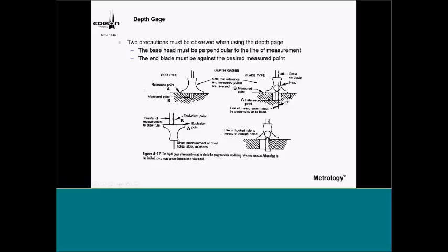And here I'll share also something we sometimes have to watch out for. Let's say, for instance, that we're supposed to have a flat bottom hole, and we have a little bit of radius here. Are we supposed to have this dimension all the way down flat on this side, or is it supposed to be at the bottom of the hole? That needs to be defined as far as your reference point.